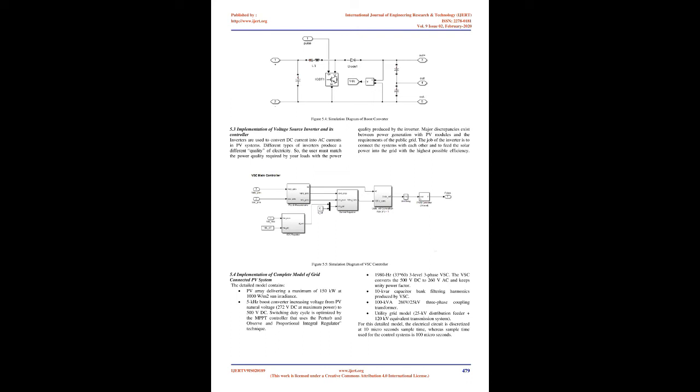3.1.5 Constant current method. Similar to the constant voltage method, this method is dependent on the relation between the short circuit current and the maximum power point current. The ratio of these two currents is generally constant for a solar cell, roughly around 0.95. Thus the short circuit current is obtained experimentally and the operating current is adjusted to 95% of this value.